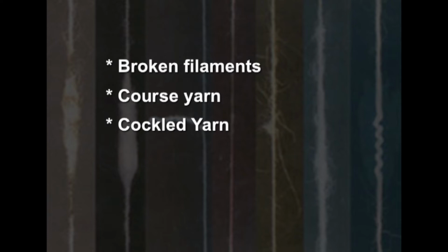Cockled yarns means small slub-like irregularities in the yarn that are readily extensible and that cause loop distortion. And faulty texturing means portions of a bulked yarn that differ from the normal yarn in respect of degree of crimp and similar distortions of the filaments.